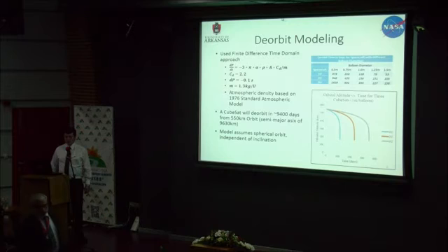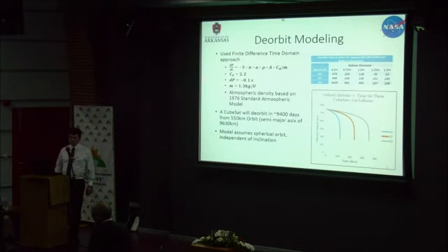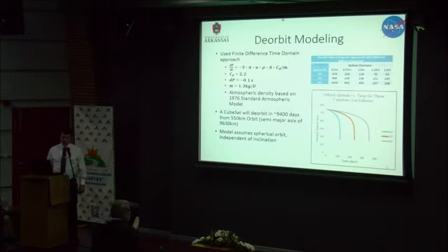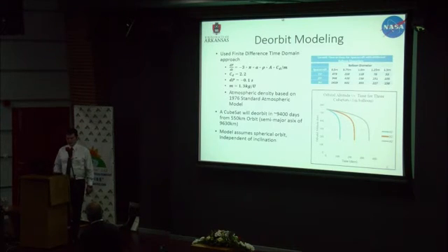The cost didn't look realistic to me because this is a nice but very complicated system, and fabrication requires special machinery. That's a good point. I put the literal cost of making that device. At the University of Arkansas, we have a microfabrication center. I get billed out at $45 an hour to use their equipment, and it takes about 12 hours to produce a wafer, which has 60 devices on it. So the economy comes from the fact that you can have many devices on a wafer.